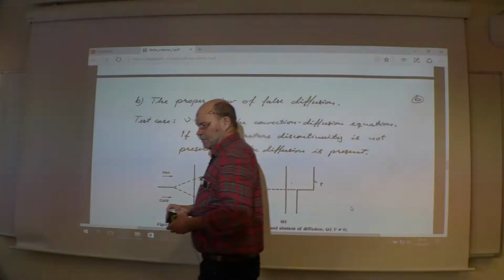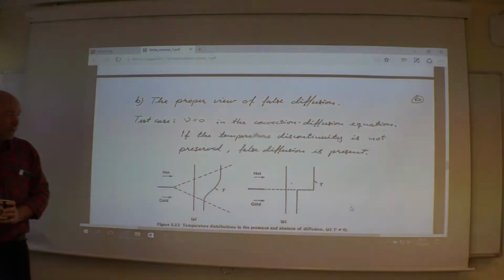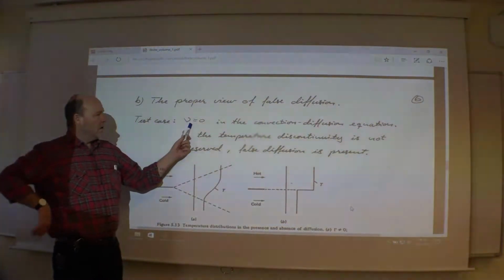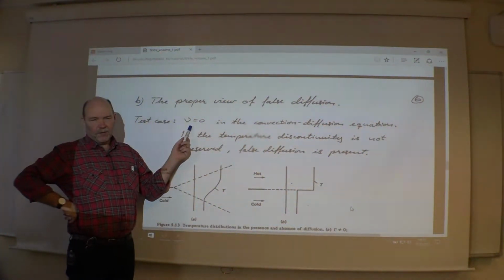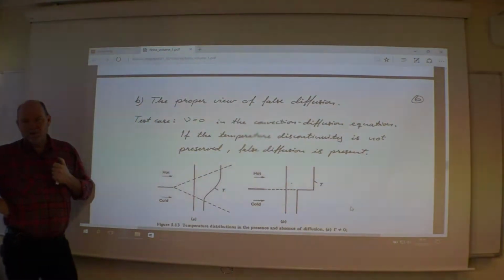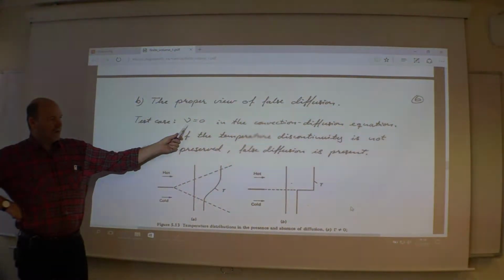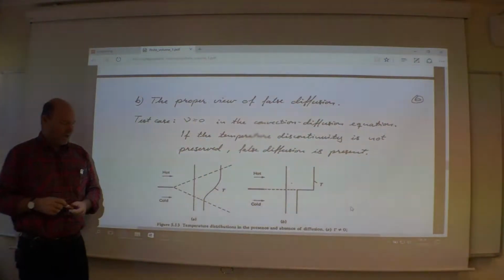And then you will see an example for it here. It's to do with the mesh, how the mesh can make a diffusion mechanism. So from the previous example, if you let the viscosity be 0, then you are left only with the transport term, only the convective term. That's all you ever have. Meaning you don't have any viscosity, you don't have any double derivatives, you shouldn't have.